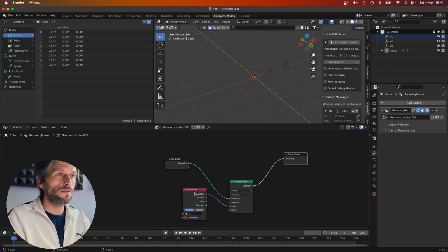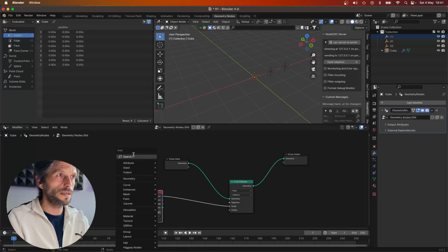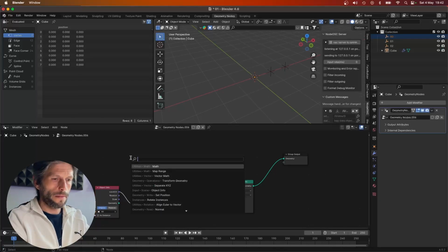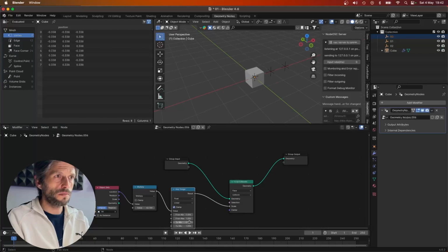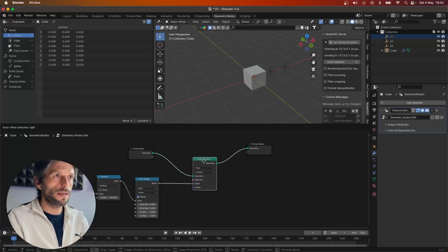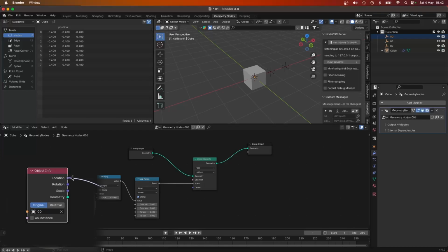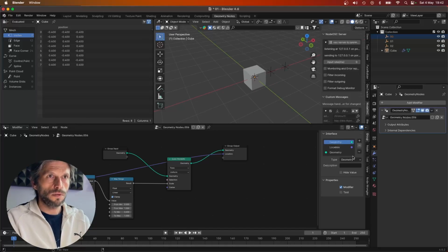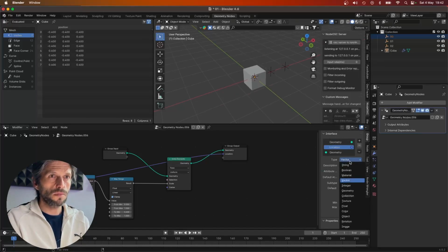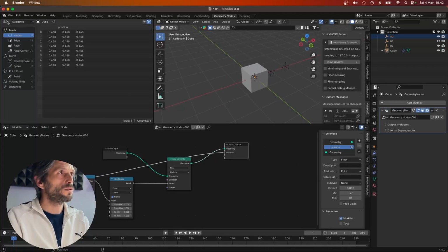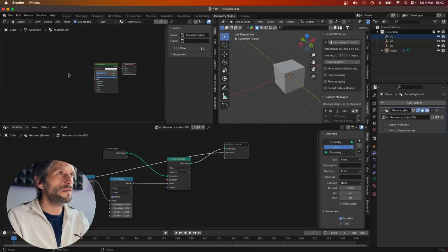Create a new node, drag the first of our node objects and use it to scale this element. Okay, using the sound of my voice, we need to amplify this signal. Okay, check, it works. Map this value from a minimum of 0.4. Okay, this is the sound of my voice driving the scale of this object. Let's see how to drive this value in shader nodes. We can send it out of the node from this. We actually output a vector, but I want to obtain a float. Let's check if it works and go to shader nodes, create a new shader.